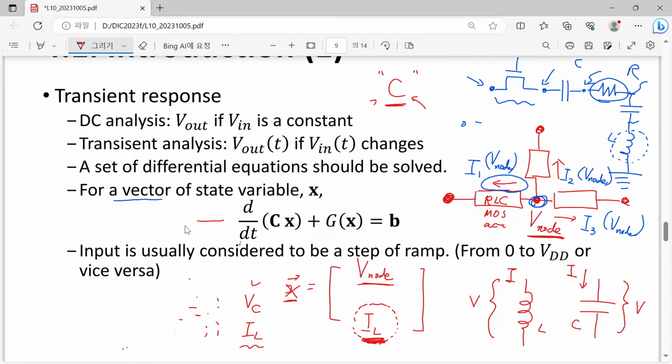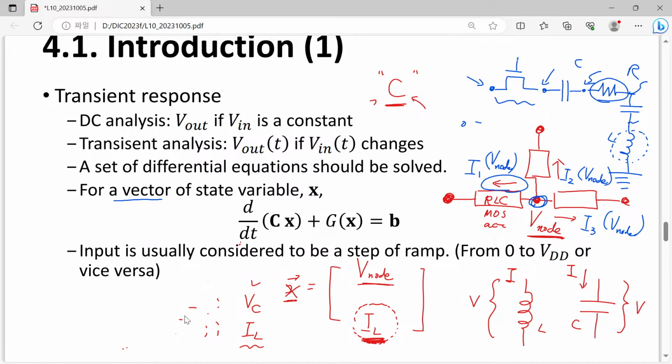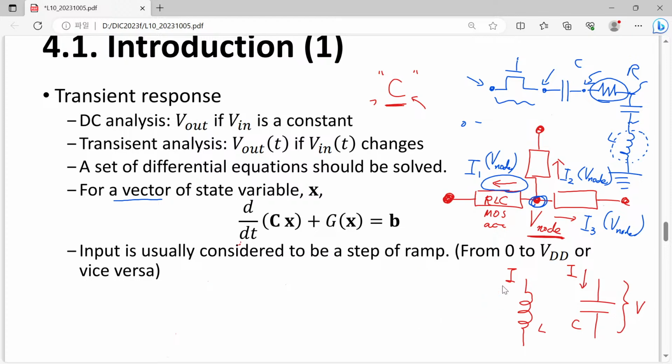Okay, so really good question. And if you still have a question, then it's okay. You can still ask me a question, or you can visit me after this session is over. So this is just a brief introduction about what happens inside your SPICE program. SPICE is nothing but just analyzing the netlist. Netlist means the text format of your circuit schematic, and inside it, it generates this large set of KCLs. Then it solves these equations.